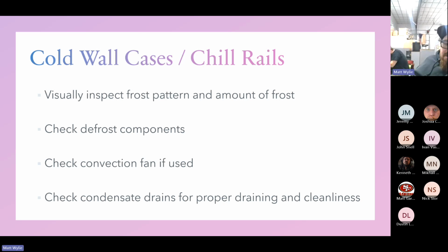Check and see if there is a convection fan used. Some of them have those fans. And then condensate drain. Check for proper draining and cleanliness.